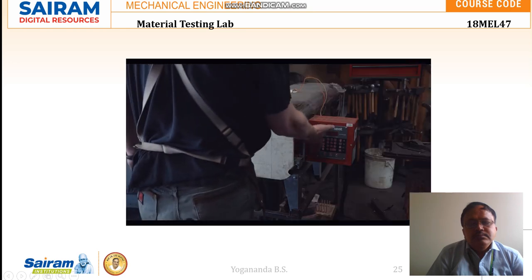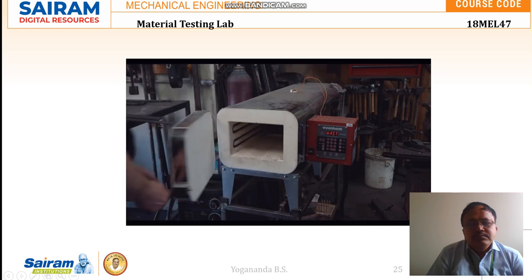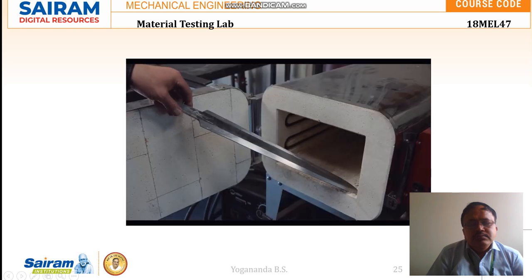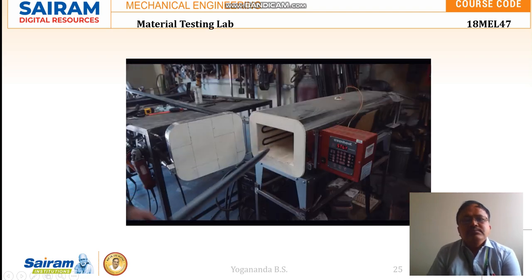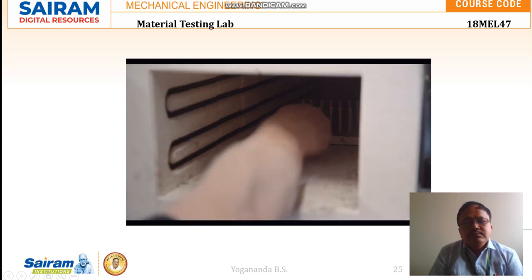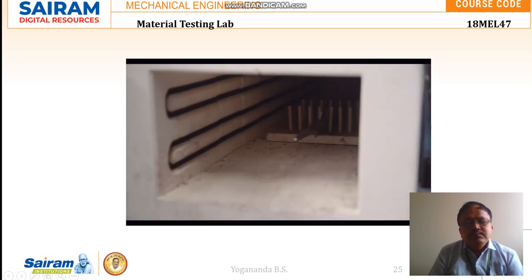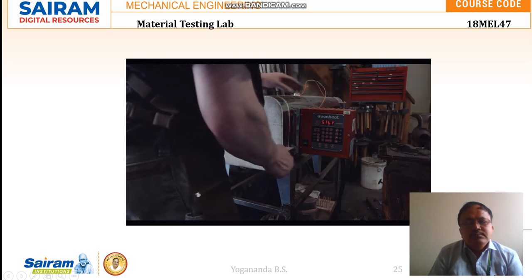My heat source for long swords is an Evenheat KF45 electric kiln. For smaller knives, I normally use the forge to bring the steel up to critical temperature. As preparation, I remove all vertical grinder marks from swords by draw filing. Another important tip is that the sword needs to be on its edge instead of lying on the floor. Putting the sword on the floor of the kiln leads to uneven heating and warping of the blade.